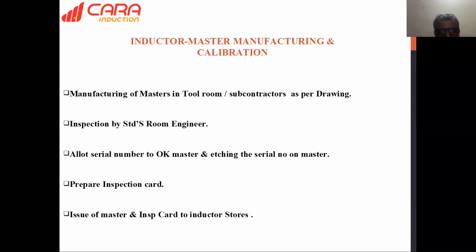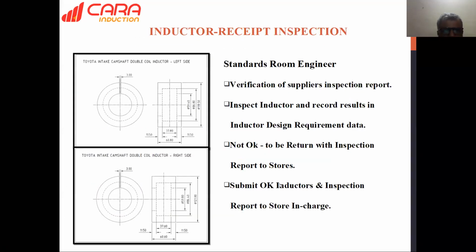We need to maintain these gaps very closely, and that needs to be checked every day or in every shift. So the inductor alignment is important, the inductor gap is important, and the checking frequency of inductor alignment with the part is important. All those things come in this section. Next, sir.